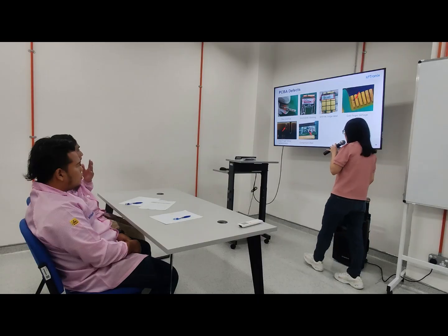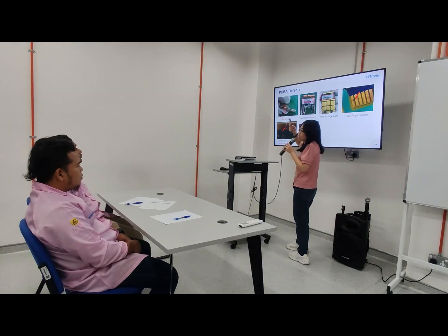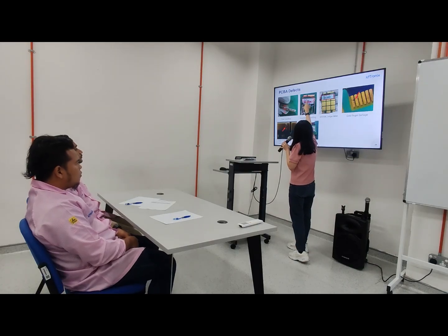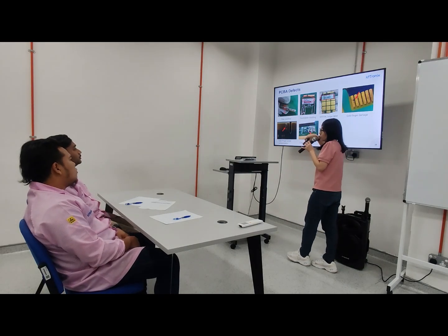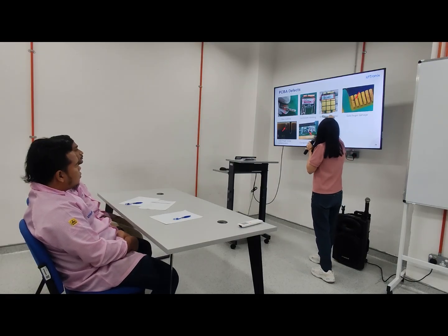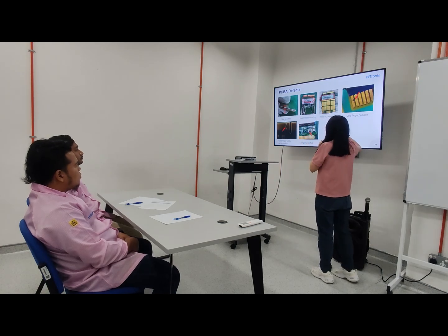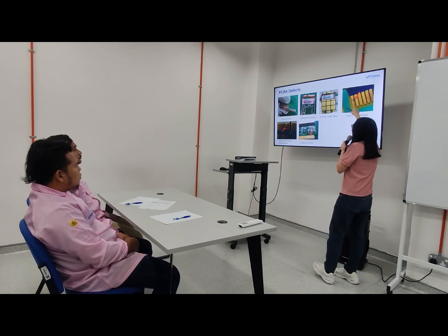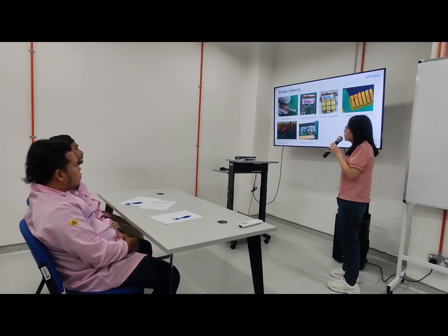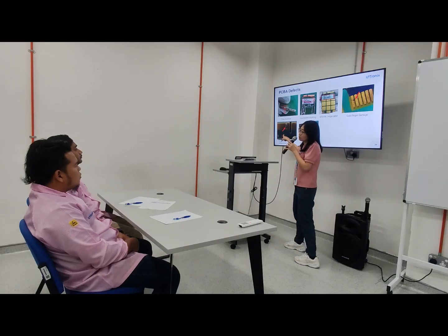Blue overflow. This is an example of blue. It has come out extra. And this is incomplete labeling. Look at the wording, incomplete printing. Wrinkle bar of label. Look at this label. It's not flat, it has wrinkles. Then we have gold finger damage. This area, gold finger damage. And we have gold finger solder contamination. This area, gold finger non-solder.